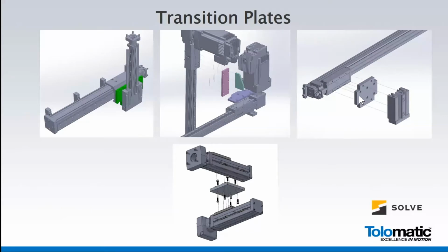But when we talk about transition plates, it's a broad term that encompasses different things, obviously. So you see, it could be a simple plate. It could be somewhat of a right angle configuration with a couple plates and a gusset, a different way of configuring those transition components. Based on the level of precision of the system, you may have different features on those transition plates. They might involve dowel pins and precise alignment elements. So that's what you see in the bottom photo here.